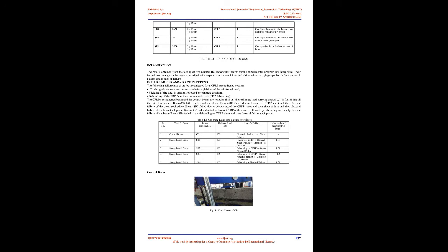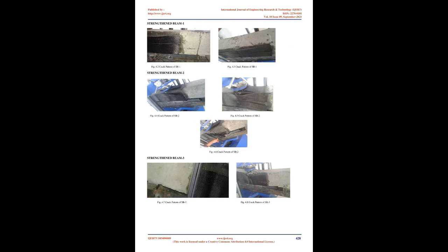The success of the strengthening technique primarily depends on the performance of the epoxy resin used for bonding of FRP to concrete surface. Numerous types of epoxy resins with a wide range of mechanical properties are commercially available in the market. These epoxy resins are generally available in two parts, a resin and a hardener. It is made by mixing base saturant and hardener in ratio 100:42. Mixing of saturant and hardener is done thoroughly for 5 minutes until components are thoroughly dispersed. Properties of epoxy are discussed in Table 3.10.